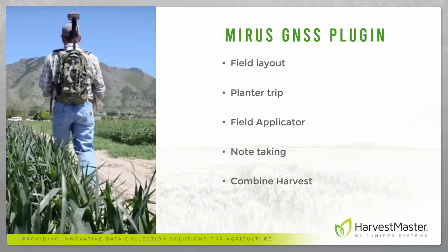And then we can add the GPS to the combine so that it will record GPS position as you're cycling. It will show you which plot you're on as you're cycling. And then you can also do some things if you're in what we call strip mode. You can cycle the grain gauge based on a set distance. So then you can create these yield maps where you cycle at a set distance and continue to harvest along, and then come back and look at that type of yield map and see variations in the field.